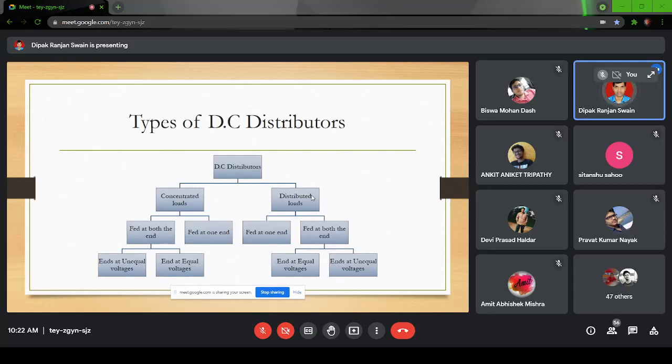As I have told, when we are calculating the RLC values or the voltage drop, we have taken the RLC values as concentrated parameters. When we take these to be concentrated parameters, our calculation becomes easy. In the long transmission line, we have not done that.